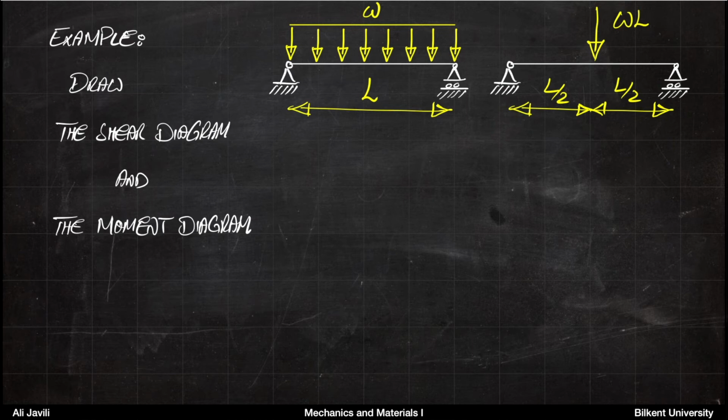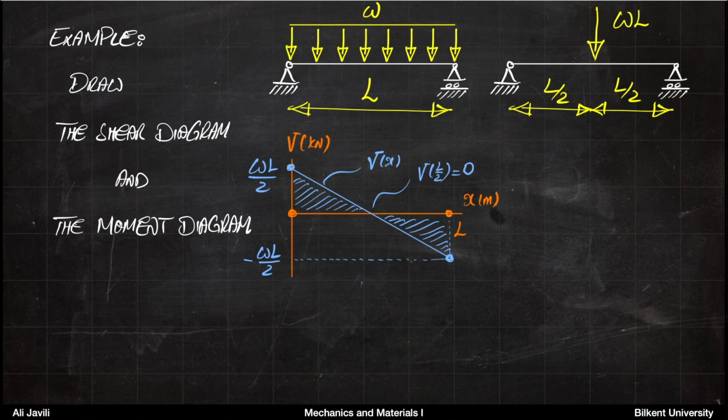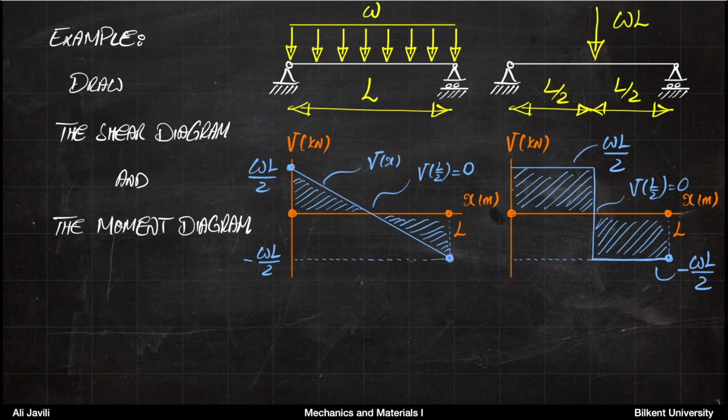But when you calculate the shear forces and moments, these two systems are obviously not identical. So if you look at the left system, we just had it. This is the shear force distribution. But for the right system, you can imagine if I have a force here, WL over 2, and I cut it here or here or here, at any point you cut it before you reach the center, you would get exactly the same shear force. So for the right system, the shear force distribution is different. It's constant until you come to the center, and then it just flips until the end of the beam.